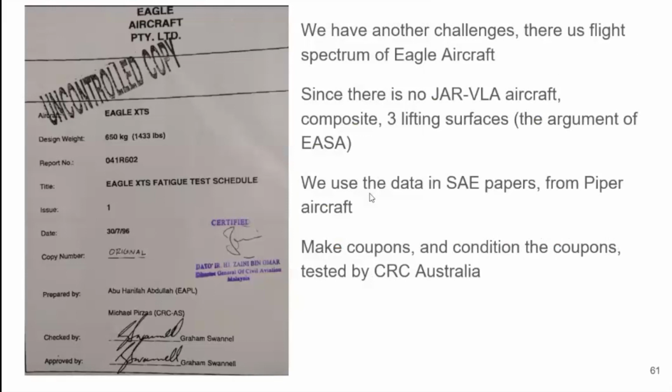As we started doing the test at the coupon level, we had a problem on the basic issue, because we do not have the fatigue life spectrum, the aircraft flight spectrum. The flight spectrum is the basis, the load that goes into the fatigue test, and we do not have that because we are just a VLA, there was no one in the market at the time, and no one was collecting this flight spectrum. The flight spectrum basically requires 2 years of flying, depending on which kind of flying, where you're flying. So we have a problem with that.